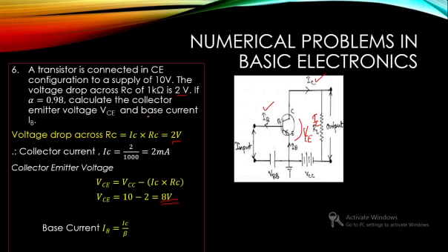And the next question is, we have to find out base current. The current amplification in the case of common emitter configuration is given by output current, what is output current? Collector current, divided by input current. Input current is IB. So from which you can write base current is equal to IC by beta. But is beta given in the question? No. Another factor, alpha, is given.